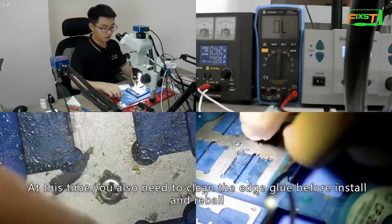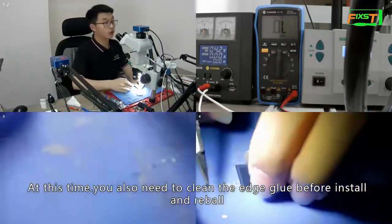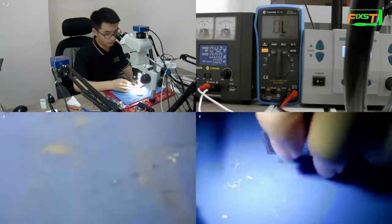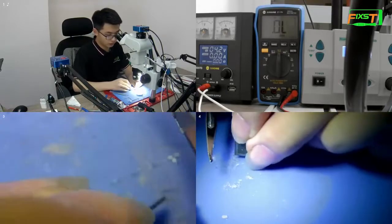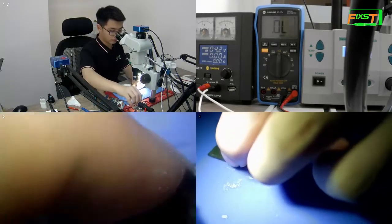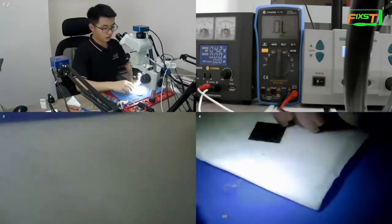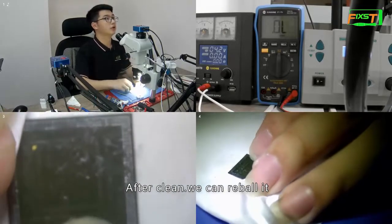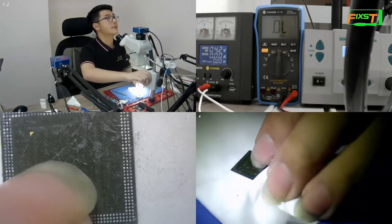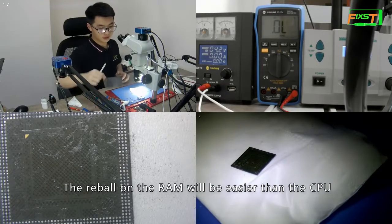At this time, you also need to clean the edge glue before installing and reballing. After cleaning, we can reball it. The reball of the RAM will be easier than the CPU.